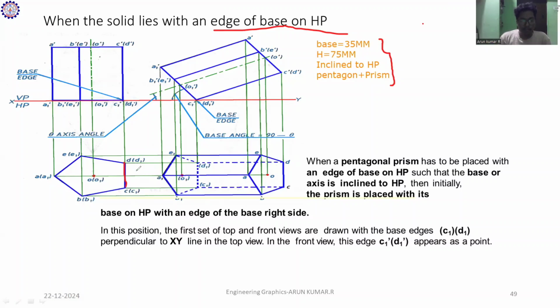Once you have considered the line, you have to place the protractor at the end of the line. There are two ends. You place the protractor over here. What is the angle of a pentagon? You know that it is 108 degrees. So with only this data available, constructing the pentagon is very easy. You place the protractor at the end, mark 108 degrees, and draw a line of 35 mm. Once you do that for both ends, you get these two lines.